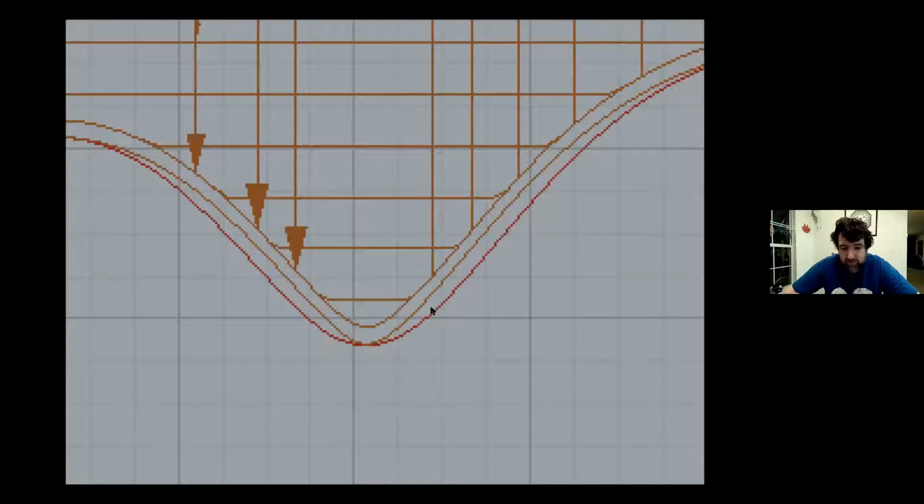But when we start to move at an angle, because the bottom of the tool is a piece of a ball, which in this case you can think of as being a circle, if the center is moving along this orange line, the place where the tool is interacting with the wood is going to always be along the red line.